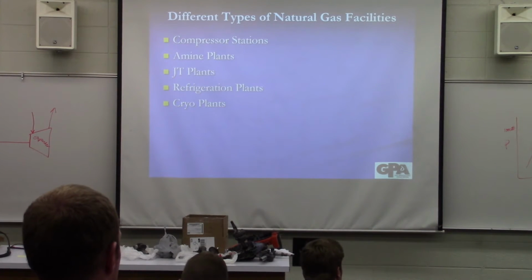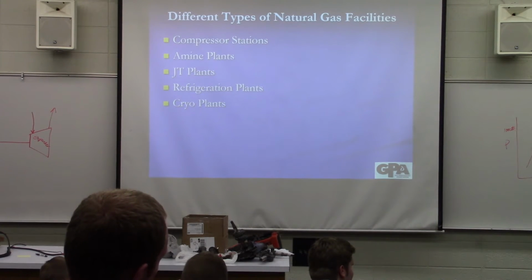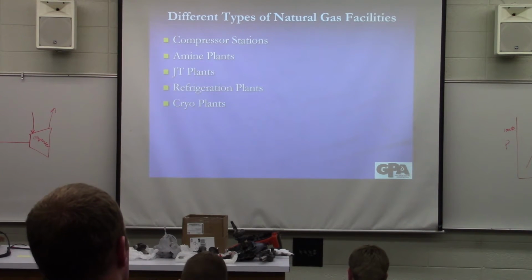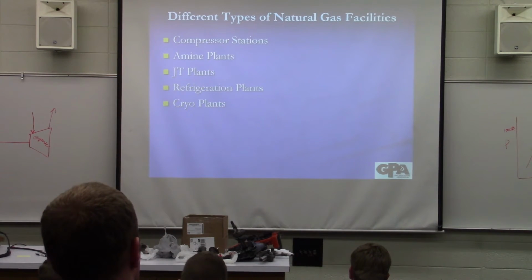And so that can be a problem in natural gas processing, where you can be sending a gas stream to an interstate pipeline, but then if their pressure drops, which it will, since pressure is the driving force in that pipeline, you could condense liquids.